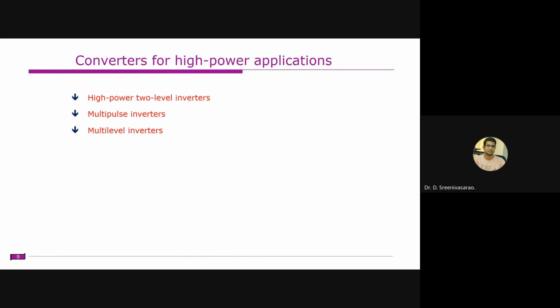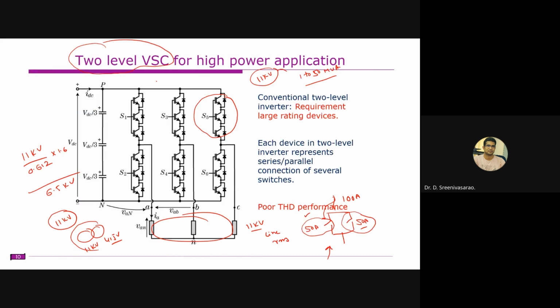So even though you exercise all this and connect several devices, it is still equal to a two-level inverter. To improve its performance, or to make the waveform close to sinusoidal, again you need to use the filters.